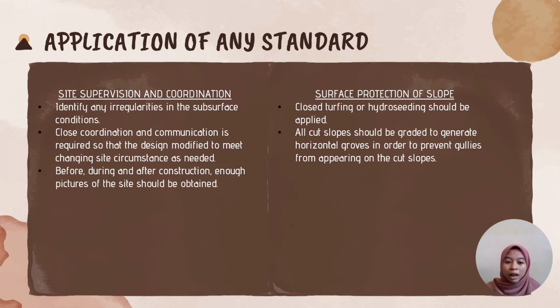Before, during, and after construction, enough pictures of the site should be obtained. These images should be accompanied by information such as dates, weather condition, or abnormalities in subsurface condition discovered during excavation. And lastly, surface protection of slope.